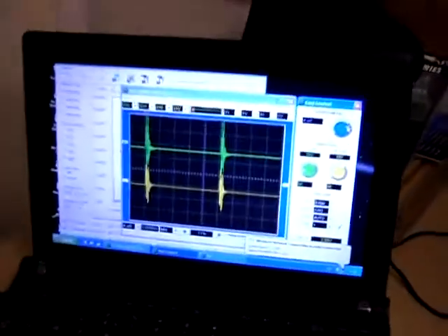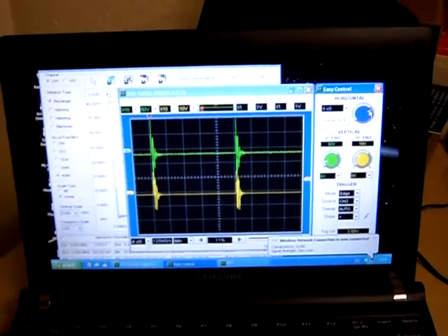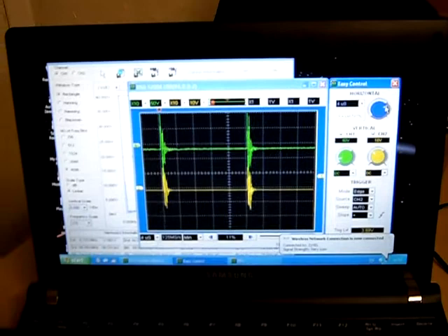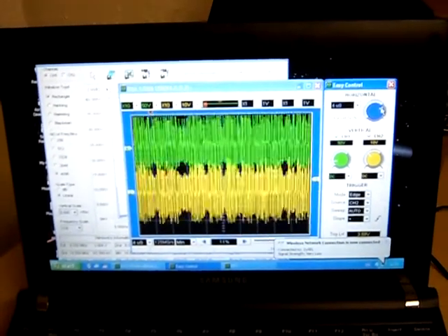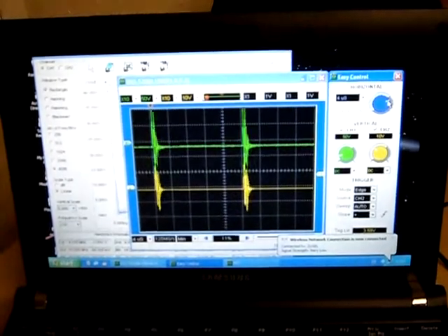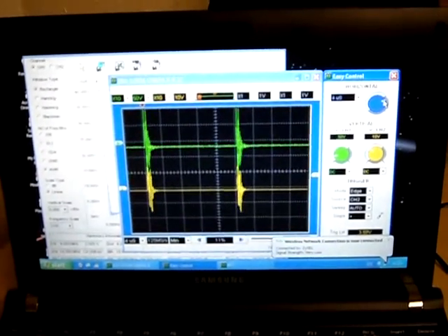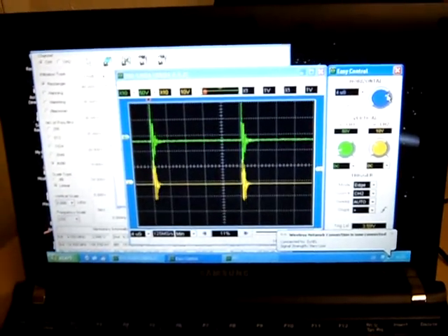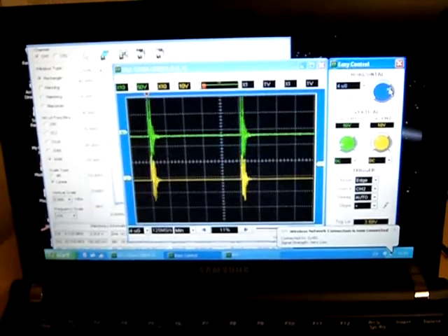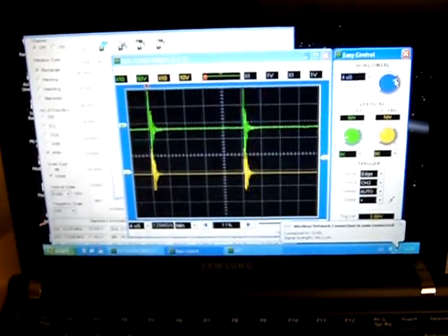Now I'm getting bursts, random bursts. The scope settings, the time base is on 4 microseconds. The green channel is actually the driven non-inductive coil, and that's on 50 volts per division. The yellow channel is just the monitoring channel. It's not actually connected, but of course it's running next to the driven coil. That's 10 volts per division.